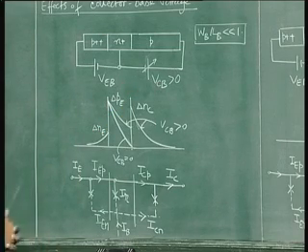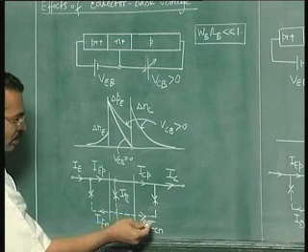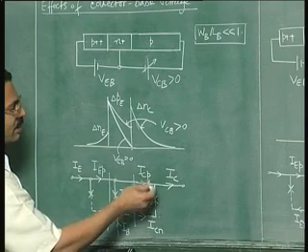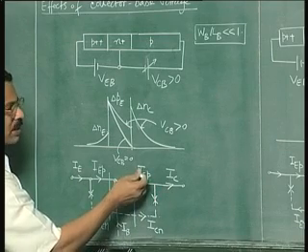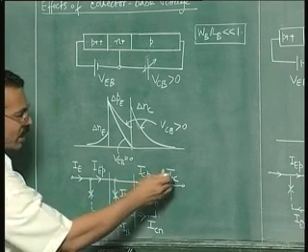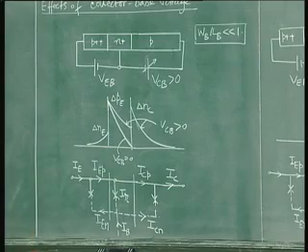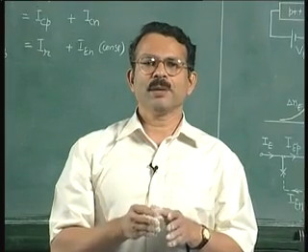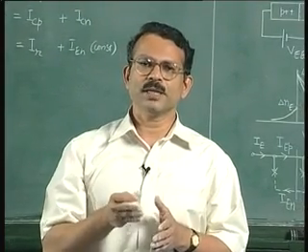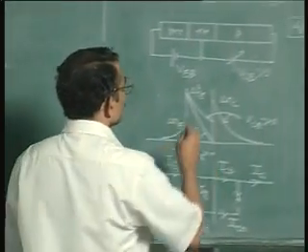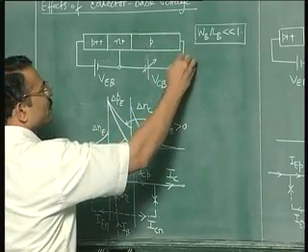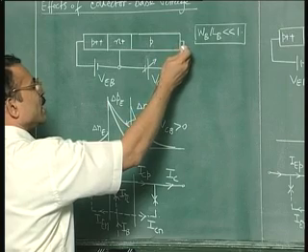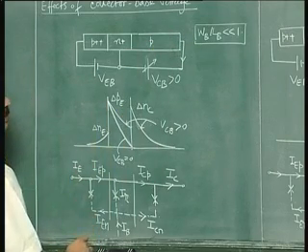So that is really a bad situation, because rapidly as you increase the forward bias, this current will start increasing, and therefore it will subtract from this particular hole current which is injected, and your collector current will start falling. And you can have a situation where the collector current becomes 0 and it even becomes negative. That means the collector current in this direction is reducing, it is becoming 0, and the collector current may start flowing into the collector.